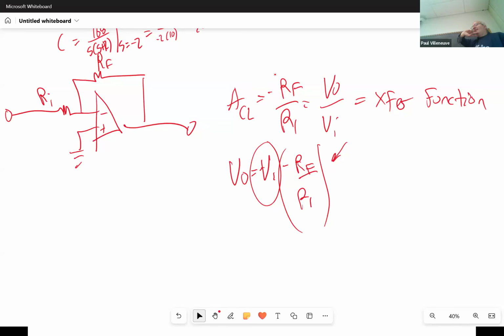Those are called air operated valves, and that would have a transfer function depending on the amount of air that goes in or out is how much that valve opens or closes. You don't see a lot of those valves anymore because it's almost always been replaced by electrically operated valves. They'll have an I to P or maybe an actual direct current to position valve. And if you give it like 7 milliamps, it opens the valve up to a certain amount.